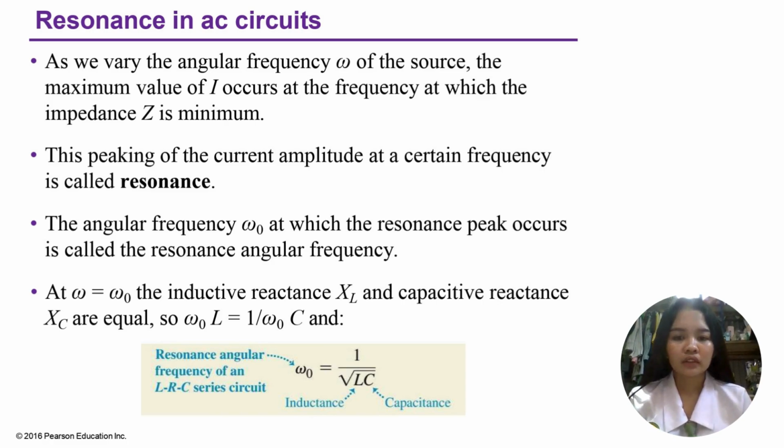At the resonance angular frequency of an LRC series circuit, the inductive reactance X sub L and the capacitive reactance X sub C are equal. So the resonance angular frequency of the LRC series circuit is omega sub 0 equal to 1 over the square root of LC.